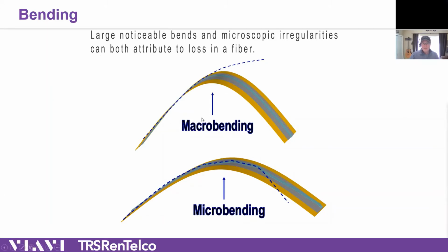The good news, macro bending. Depending on the OTDR you use, if it's ours, and my competitors do this too, so I'll just say most of them, most of the higher end OTDRs will not just shoot a single wavelength to characterize your cable, but they'll shoot 2 wavelengths, like 1310 and 1550. So you guys who use OTDRs have seen that. The reason for both of those is twofold.